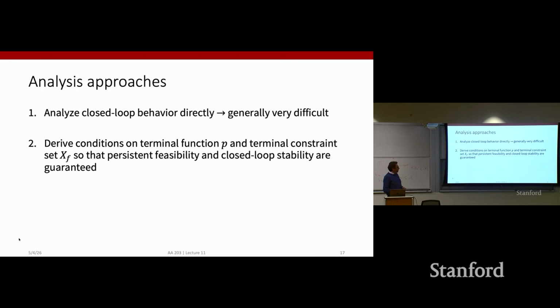So there are two possible ways of approaching the problem. The first one is a closed loop system, right? So we have x t plus 1 equal to f closed loop of x of t. We try to analyze how the dynamics of this closed loop system evolve depending on the three tuning knobs, and then we optimize the three tuning knobs.